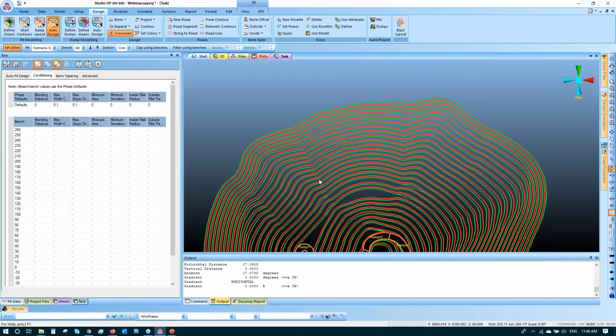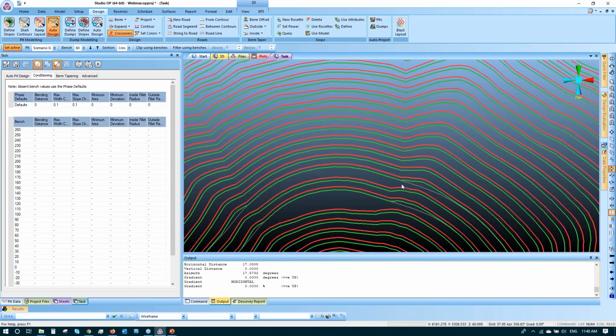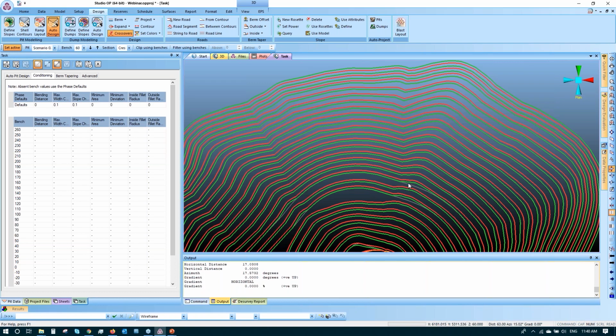As you can see by these wedges here and here, this is the range of azimuth that I'm expecting. And since over here, where I was squaring the points, is where my blend distance starts and my slope region starts to change, my berm width starts to change as well, from 12 to 17.